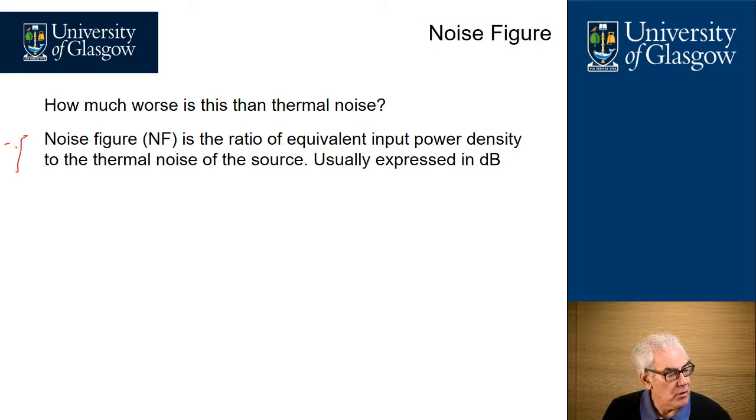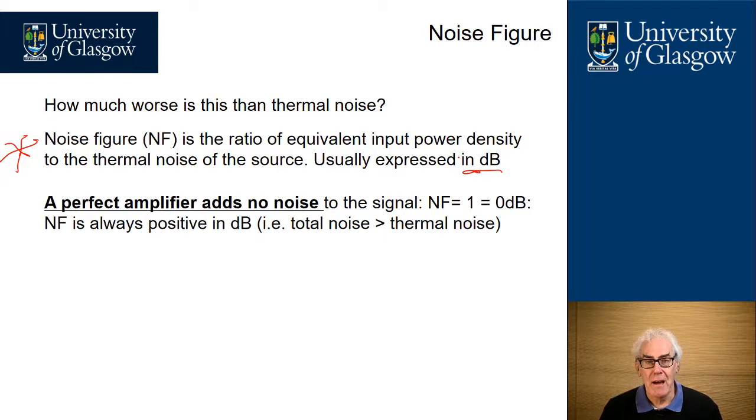First of all, you'll recall that the noise figure of an amplifier is the ratio of the equivalent input noise power from the amplifier compared with the thermal noise just off the source, and we usually express it in decibels. Remember that a perfect amplifier will add no noise to the signal whatsoever, so the best noise figure you can possibly attain from any amplifier and any circuit is a noise figure of 1. But given that all amplifiers will add noise, the noise figure is always positive in dB, i.e. is always greater,